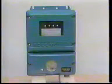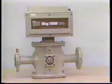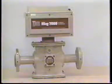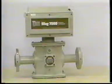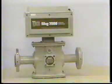Another important class of flow measuring devices is the magnetic flow meter. The magnetic flow meter is a volumetric metering device. Its operation is based on Faraday's discovery that electrical currents are induced in a conductor that is moved through a magnetic field. Let's look at an illustration to see how this is used in a magnetic flow meter.